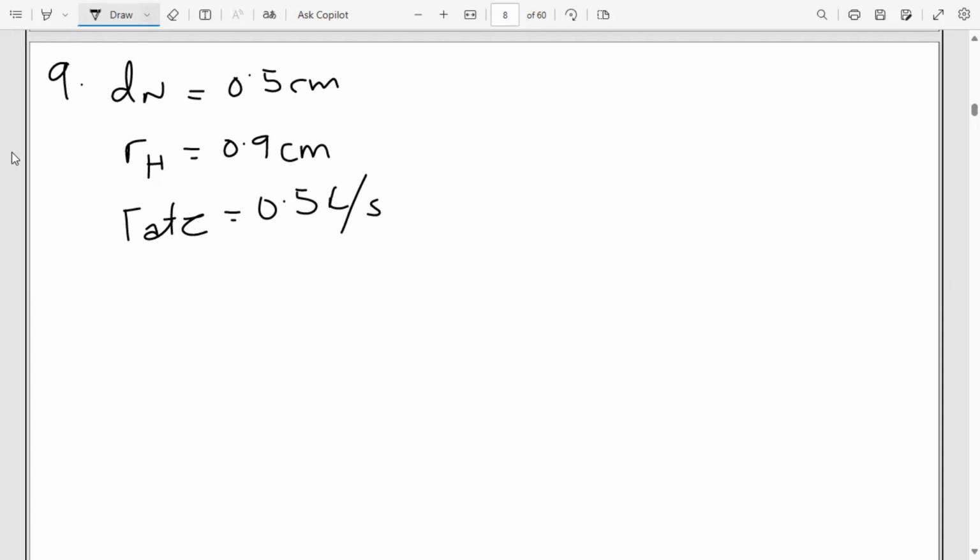And we know the SI unit for volume is the cubic meter, whilst the SI unit for time is the second. So we're supposed to convert this into cubic meters per second. And this is actually going to give us 5.0 times 10 to the power minus 4 cubic meters per second. So this is the flow rate in its SI unit. Now that we've converted our flow rate, we're supposed to find the cross-sectional area of both the nozzle and the hose, provided the radius and the diameter that we've been given in the question.